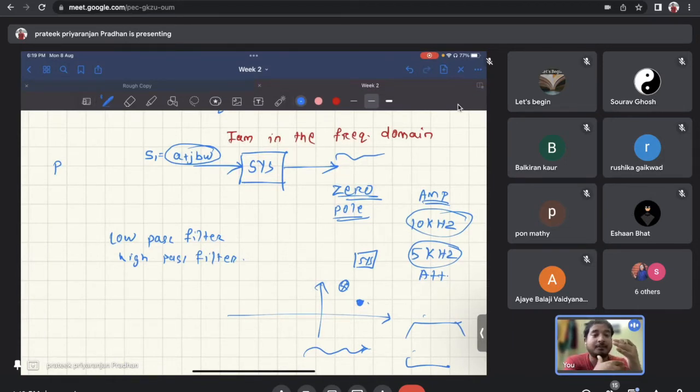You want your system to behave like this: say my working range in the frequency domain is 2 to 3 kilohertz. The rest of all the signals are noise and you want to attenuate them, then you can add the zeros there and the poles over there. Is it clear why poles and zeros are important?